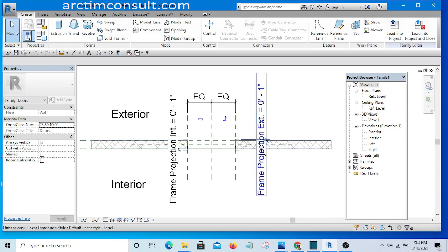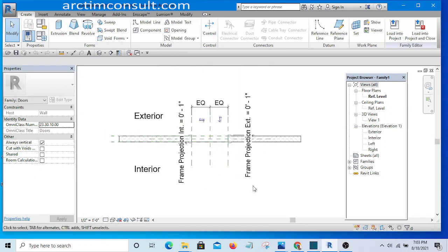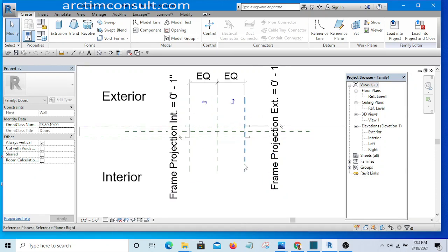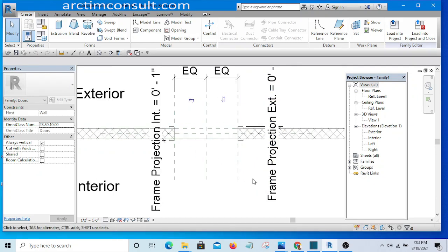Now the most important thing you will see here is that the dimensions are given in imperial system. So the first thing I want to do here is to change the project unit to metric system. That is the one I understand most, and the one most Africans understand, which is millimeter, meter and centimeter.